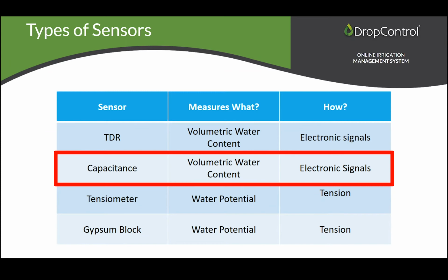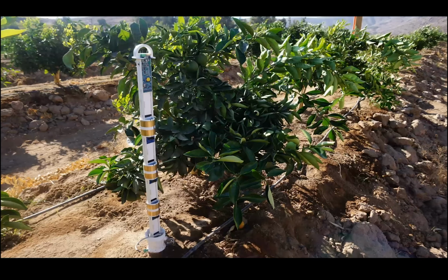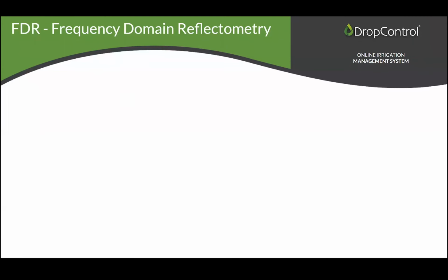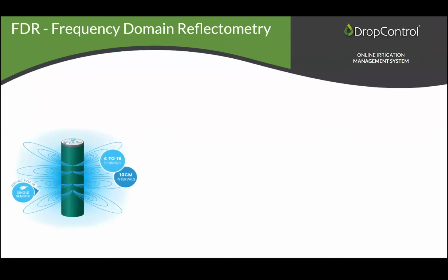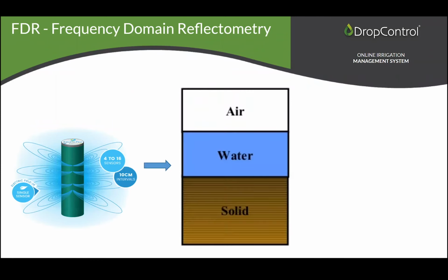So that was solved with the FDR technology, frequency domain reflectometry, and in most cases it's presented as probes. So they are probes that are inserted in the ground, like the picture that you can see now: you auger a hole, you install the probe, and the probe sits there and measures moisture through the vertical horizon. So I was saying FDR, frequency domain reflectometry, is basically reading frequency, and the sensors have an electric field around the sensor itself that is basically measuring the percentage of water.